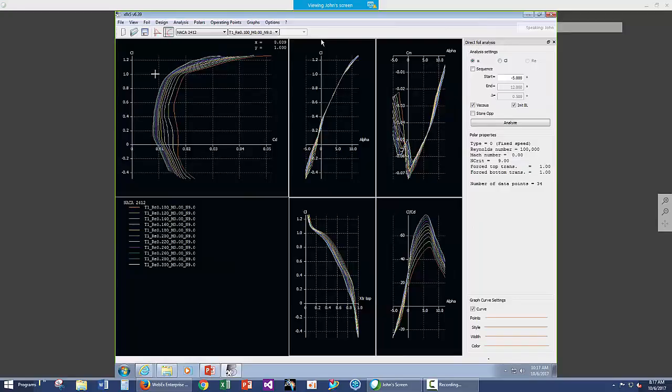What we'd like, and what we would get if we went to some of the Selig airfoils or the Wortmann airfoils, is a much straighter curve, so we wouldn't get so much drag up at the top. On CL versus alpha, we're not quite up into the stall region. Sometimes when we move up there, it has trouble interpolating and gives us an interpolation error. We probably are not going to fly up there. Maybe on landing we'll get into that configuration.